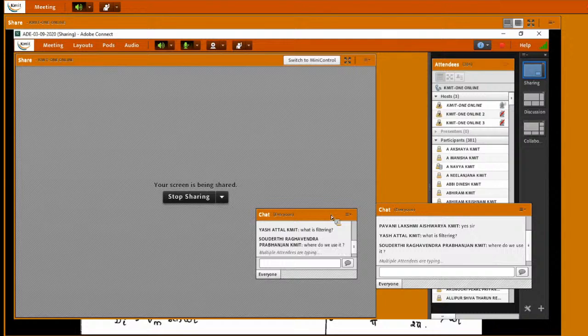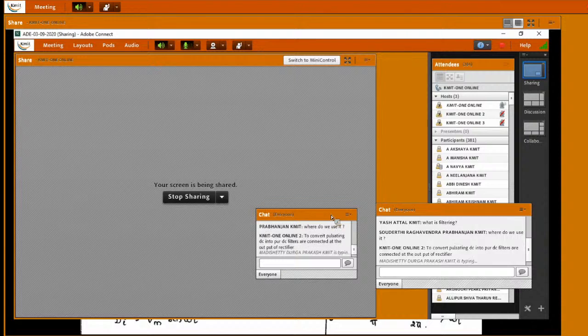If you use the rectifier, it will convert the AC signal to a pulsating DC signal. Then we need to convert the pulsating DC to pure DC. For example, if our mobile phone does not get pure 5 volts DC continuously, the device is going to be damaged. We need a constant DC power supply for electronic gadgets. The rectifier alone does not give constant pure DC; its output is impure DC.